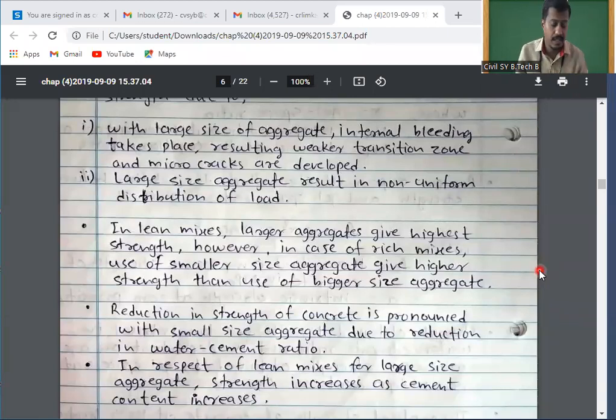In cement, I think in my first unit, I have told you how the bonding works. If the cement particles are finer, that is why the fineness test is very important for us to understand the concrete phenomenon, because the finer the cement, the greater the surface area, and with greater surface area there will be more proper bonding between the cement and the rest of the concrete particles. That is why we are preferring the finer cement. The same rule applicable to coarse aggregate also.